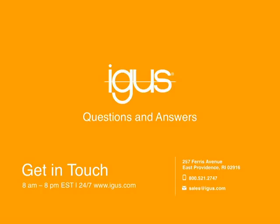Okay, another question here. Good question. What happens if the parts do get lubricated? It's generally not a problem to lubricate our parts. In fact, a lot of people who own agricultural equipment or lawn care equipment may lubricate our parts even though they don't require it. They won't hurt necessarily. We do have a list of usually petroleum-based greases or oils that are fine for our parts, but all of our lab data in the catalog is based on dry running applications.